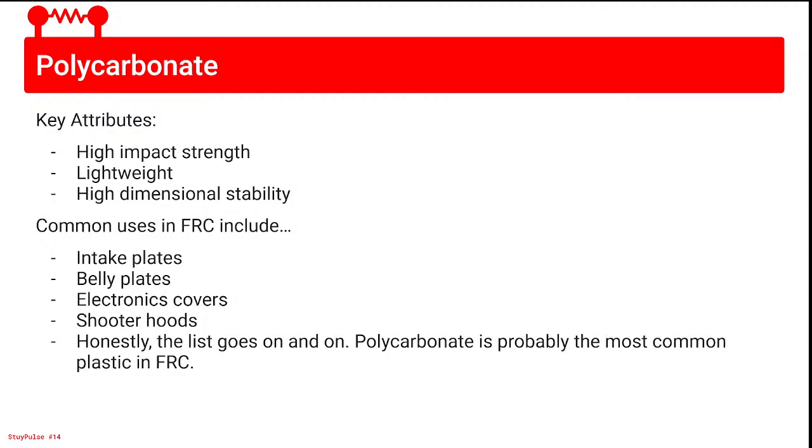Yeah. I'm not going to say it's my proudest moment, but it worked. And it's still working, like it's still here, so I'm not going to say anything about it. But after that, you're very against using Lexan belly plates simply because using 1/8" aluminum and 1/4" polycarb, similar in weight, things like that, but you could get away with pocketing aluminum and just lessening that in the weight in that regard, but it's still a lot stronger than 1/8" polycarb.